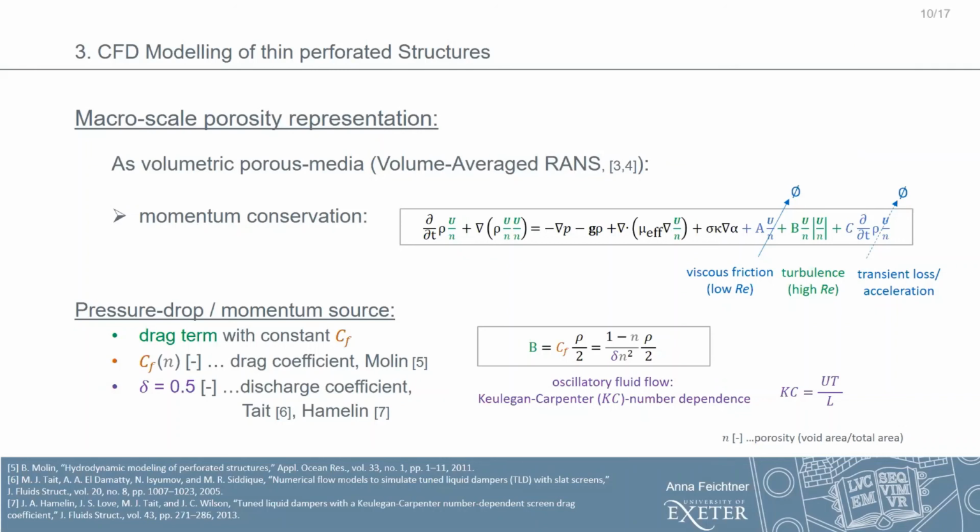Specifically for the pressure, in general at the outlet there is this active wave absorption method, which applies the velocity profile of the used wave condition in the opposite direction. So kind of a cancelling out of the wave takes place there.